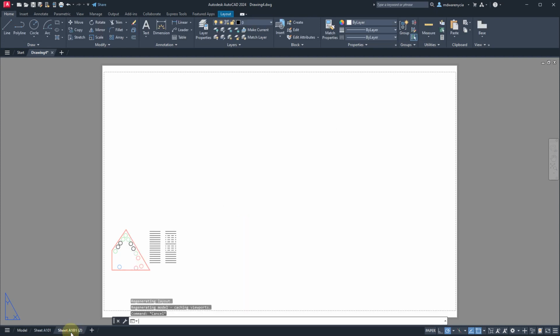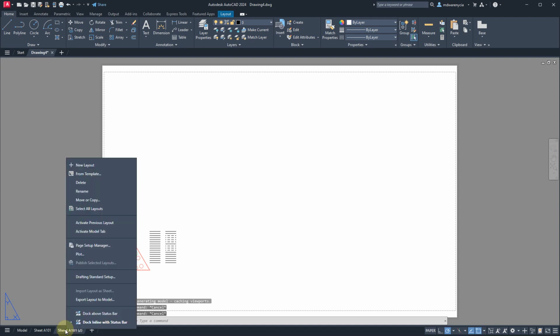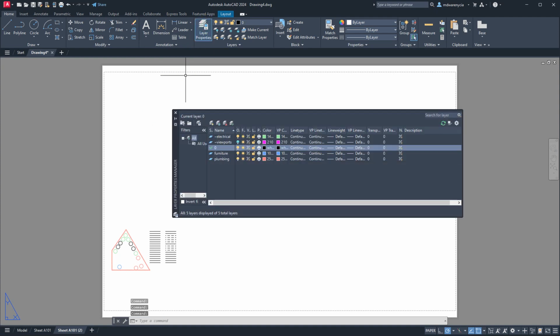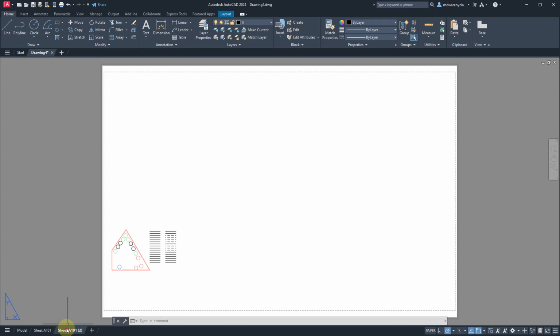There's a shortcut that doesn't work there for rename, but if you're in the layer properties, sorry, OCD's taking over here a little bit. I'm jumping around a bit, but if you hit F2 here, it's a little bit better than doing a slow click. I think that's how a lot of people end up accidentally switching layers. If you just hit F2 on the keyboard, it'll bring you into a rename mode in a lot of things in Windows. Not here though. You'll have to go in and manually change this to A102.